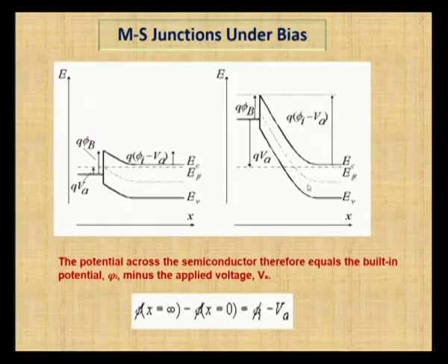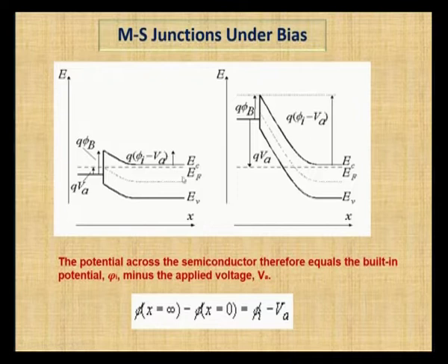The semiconductor junction with positive barrier height almost acts as a rectifying device and has rectifying behavior. When we give a positive bias for an MS junction, it almost acts as a rectifying device. A large current exists under the forward bias and there will be no current in a reverse bias. This is a comparison that we can make between forward and reverse.